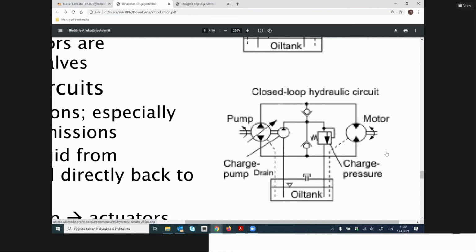And it is very simple and very straightforward, and it works very well in excavators or forest tractors when you have these slow driving speeds, but you need very high torque. But like I mentioned, when you go to drive on the road, the efficiency becomes very poor, and then it makes sense to have the normal mechanical gearbox or something like that instead of this.